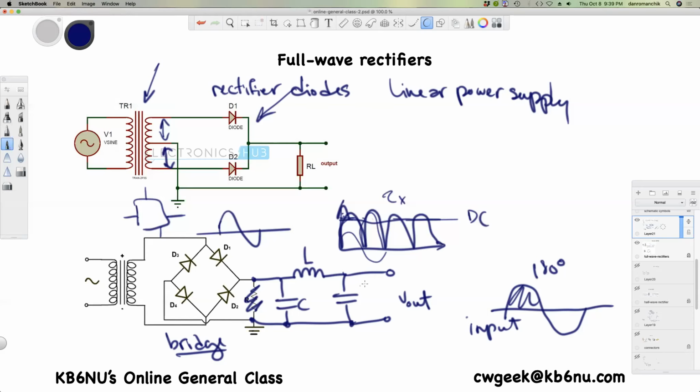And then if you know you're supplying a lot of current here and these are big capacitors, you might want to put a high value of resistor on the output here, you know, 1 megohm or something. Why is that? Well, when you turn the power off, the current will then go through the resistor, the power off to whatever load you've got out here, the radio, or whatever.